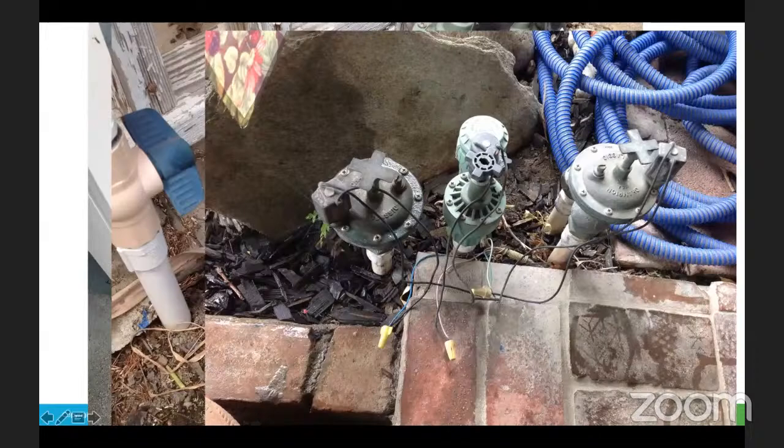Sometimes that's just what's needed. And typically we want to repair like for like, is what we call it in the industry. So these were the original brass anti-siphon valves, and this is called a brass adapter. They replaced the brass valves with a plastic valve. You can see it's a lot smaller of a valve, so the flow going to the system is a lot less, I should say. Ideally, you would want to replace it with the same type.